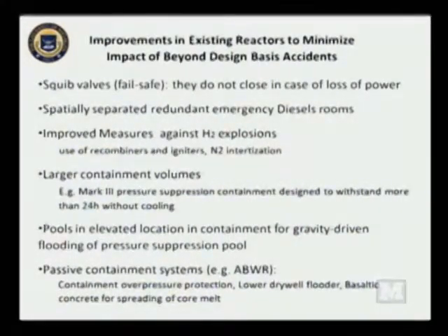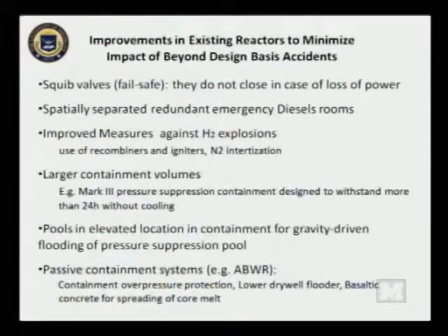And you want to do that so you can inject the emergency water into the reactor. And to do that, the pressure has to go low. But what happened in Fukushima is that after they lost the power and also the diesel generators, the valves which they had installed on the RPV got closed because they were powered by some additional batteries, and once these batteries expired in something like 5 hours, these valves reclosed, and so the reactor pressure vessel started to pressurize again, which was really bad. So in existing plants, unfortunately not in Fukushima, these squib valves are installed, and these valves do not close once they have been opened.